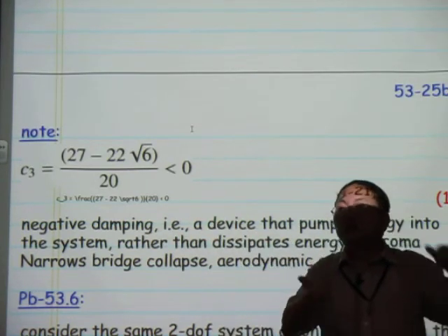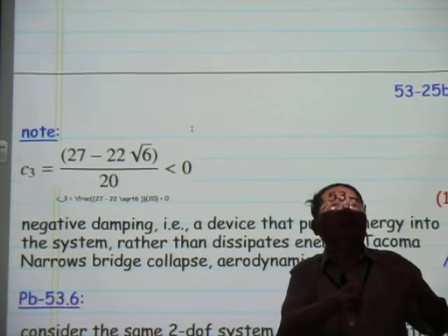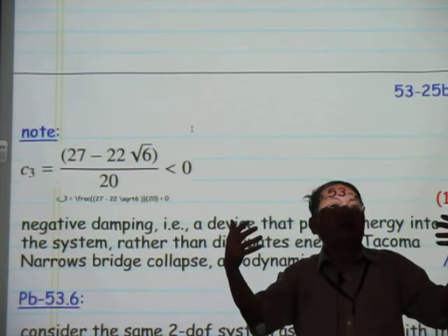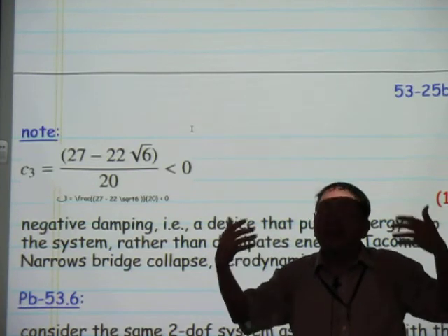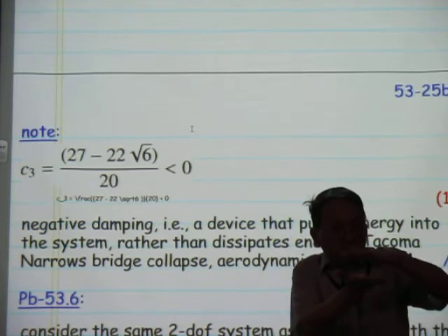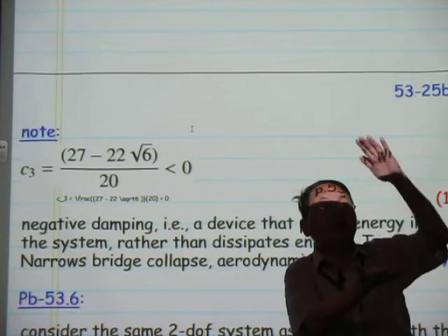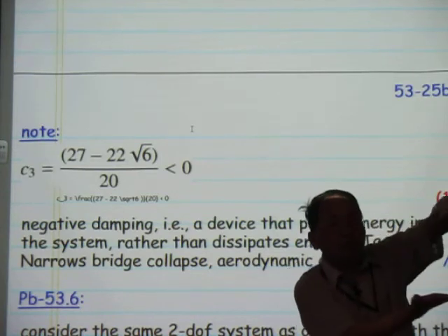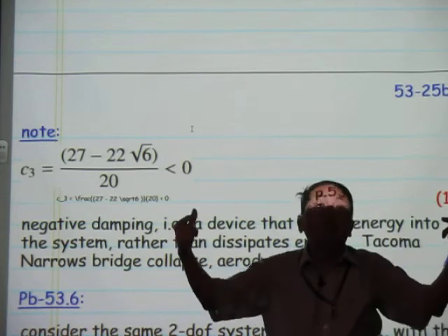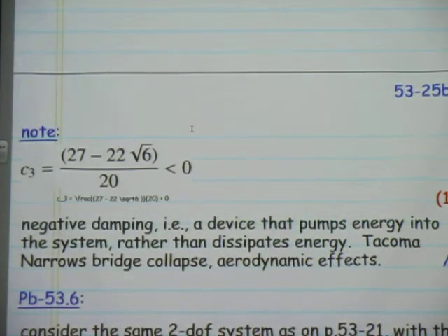It's due to the self-exciting aerodynamic effect, that when you derive the equation, you have the negative damping term. And negative damping reinforces the oscillation amplitude, and the amplitude of oscillation increases up to a point where the bridge will break. That's to keep in mind.